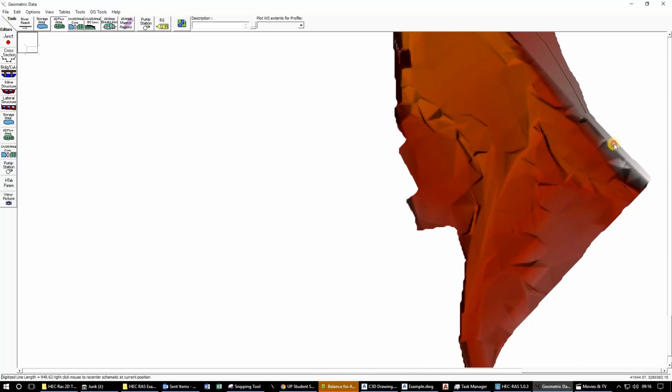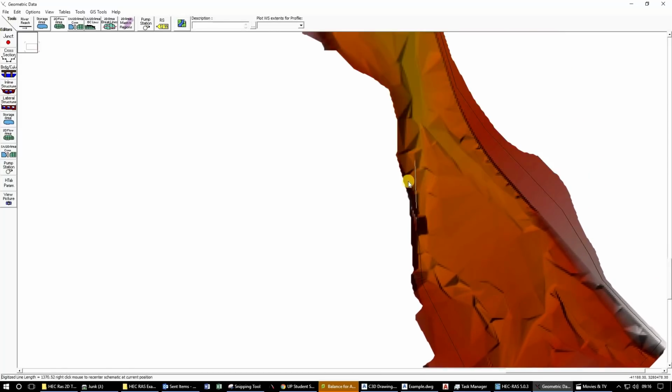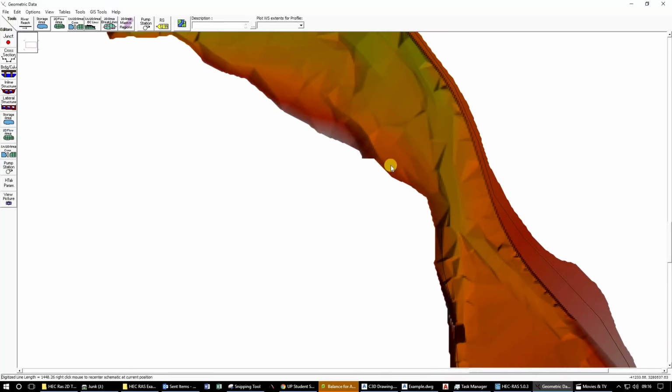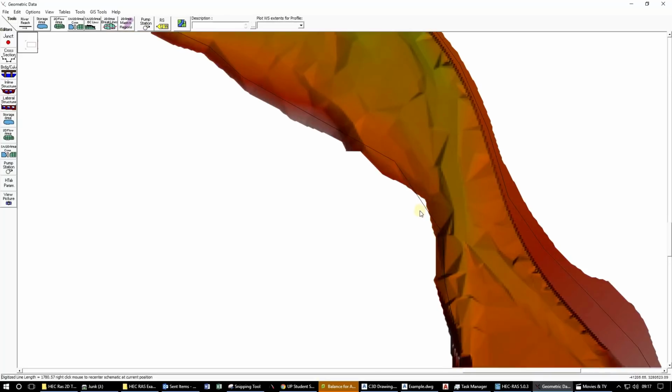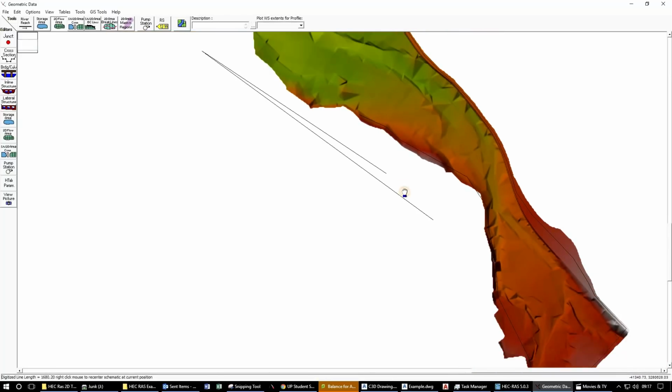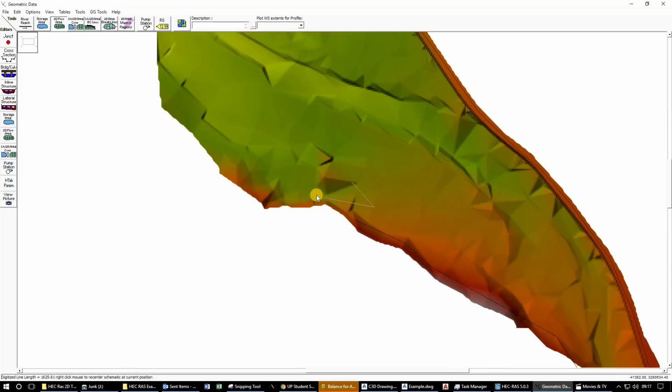What you guys should also avoid, because it is going to cause problems later down the line, is if you are not careful and you specifically click or create this 2D area so that it falls outside your land or your terrain file. So I'm going to purposefully create an error now, and then we will come back and correct this at a later stage, just to help with debugging along the way. As you can see there, I specifically missed it, so we will get errors when we create that or try to run the file.